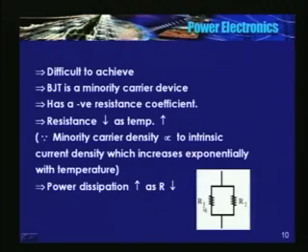So there is again a reduction in the resistance of R1, and thereby it starts carrying more current. So it goes on building up and eventually it will fail. So therefore, for any device which has a negative resistance coefficient, paralleling is difficult.